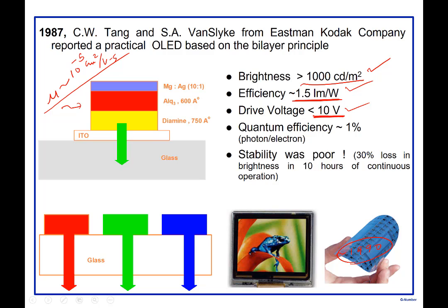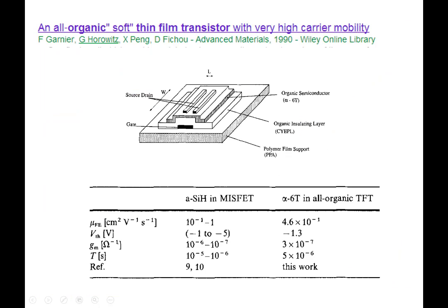So it was apparent that you could make it, because this is amorphous, just like the LCD TFT was amorphous, and therefore you could put it on any material. Similarly, organic material is also amorphous, so you could put it on any material. So you could get a flexible display also. The moment you work with amorphous semiconductors, you can deposit them on a large variety of substrates: metal, plastics, wood, cloth, all of these things in principle, okay? And thereby have lots of interesting applications.